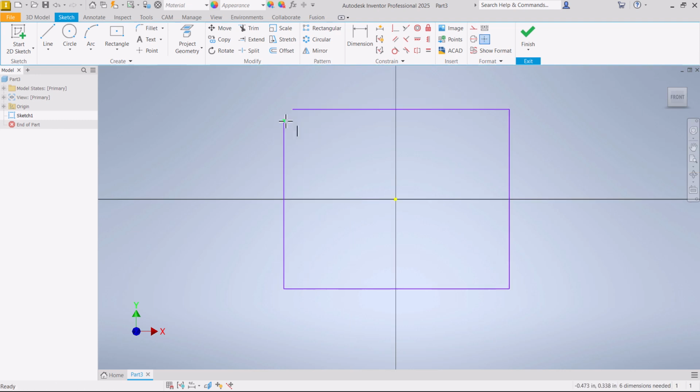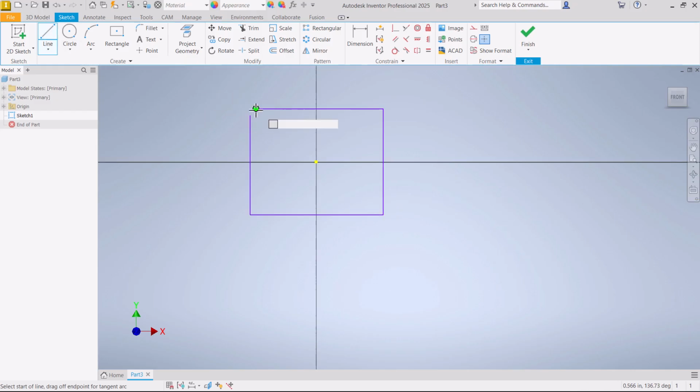One thing that you'll probably run into pretty often is that you sketched some shape and then you get out here and you realize you didn't stick those last two endpoints together. If you notice that, or if you had some other geometry out here, say you thought you were going to draw something else, but then you decide you need to delete something, you can just come in, use coincident to close that box, because to create an extrusion, you have to have a closed profile.